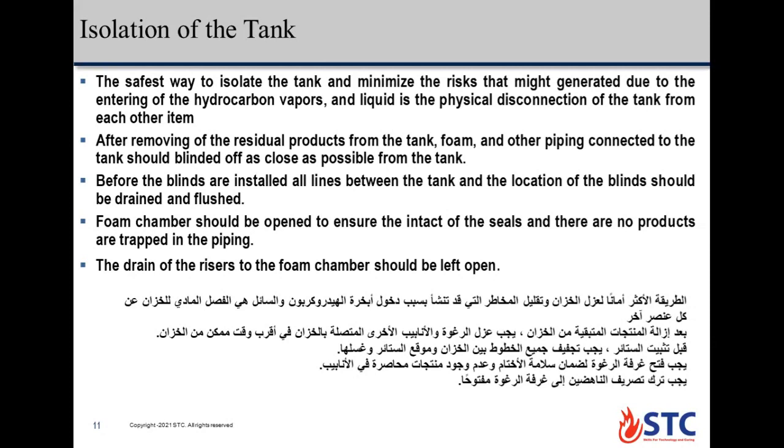Okay, and after removing of the residual product from the tank, pumps and other piping connected to the tank should be blinded off as close as possible to the tank. Again, after removing of the residual products from the tank, pumps and other piping connection,